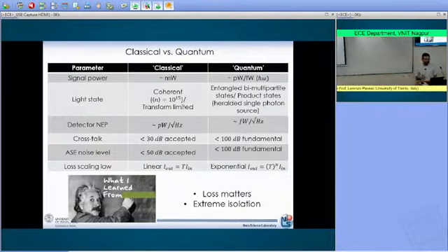The crosstalk: you remember yesterday we discussed crosstalk, and we said that we can accept a crosstalk between different channels in an optical network that is smaller than 30 dBs. In the case of quantum photonics, any filter that we are going to develop should be able to filter out down to the single photon level, meaning that now the requirement is extremely more severe.